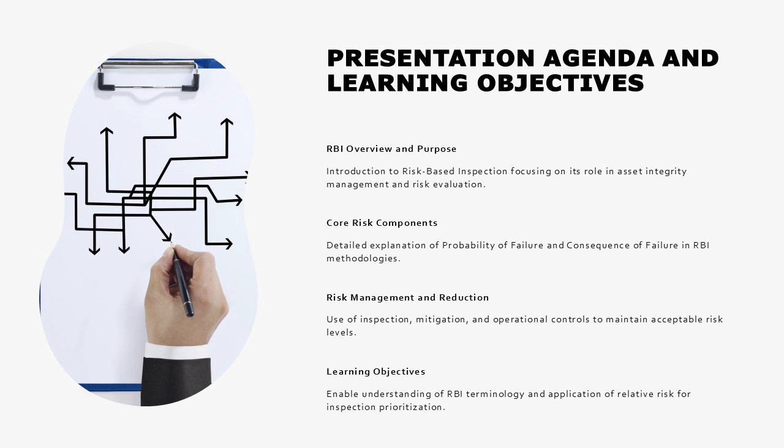Throughout the presentation, emphasis is placed on practical application, alignment with API RP 580/581 guidance, and consistency with engineering best practices. The learning objectives are to enable participants to understand RBI risk terminology, explain how risk is evaluated and managed, and confidently apply relative risk concepts when prioritizing inspection and mitigation activities. These objectives support effective participation in RBI assessments and informed decision-making within multidisciplinary integrity teams.